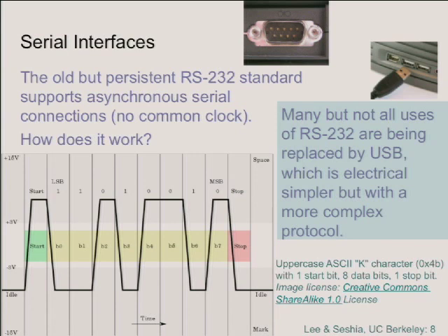So you need cables that reverse pins 2 and 3 of the DB9 connector so that the sender is at one end, the receiver is at the other end. So pin 2 at this end is connected to pin 3 at this end, and pin 2 at this end is connected to pin 3 at that end. And if it's not that way, then both devices will try to send on the same line, and they will have a short circuit. The RS-232 specification in the standard tolerates those short circuits by saying you have to have a certain amount of impedance in your interface so you don't fry the other guy, even if you're both asserting opposite voltages on the line.